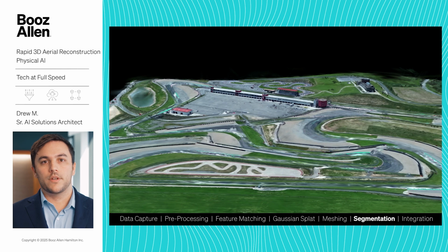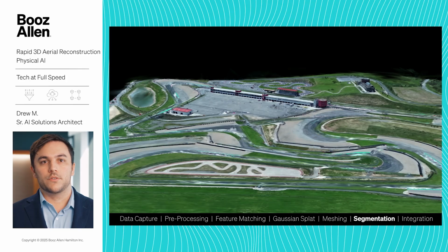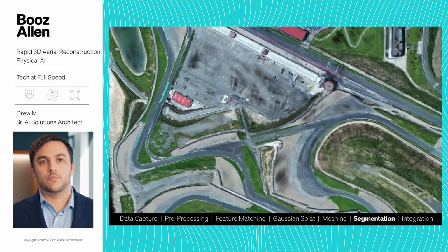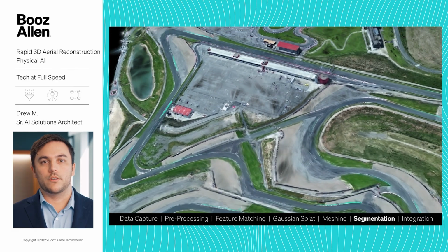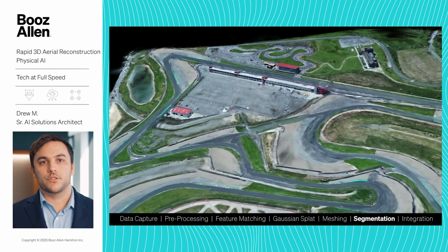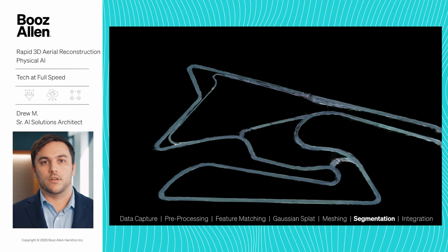We then perform 3D segmentation of this output using semantic segmentation techniques to provide an additional layer of metadata that we use to tie physical properties to the visual data. For example, this segmentation model can be used to extract dirt or road material from the data as an image mask. This can then be applied to a roughness texture to the material of the 3D mesh, which will then in turn affect the friction of the material as a ground vehicle drives across it.